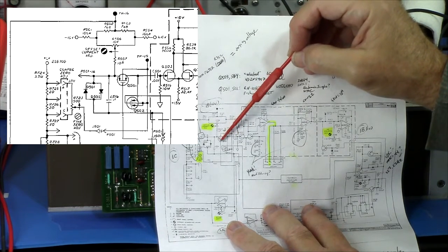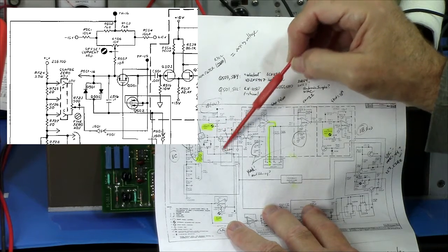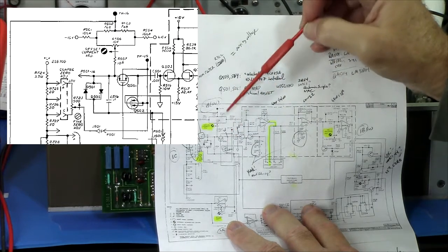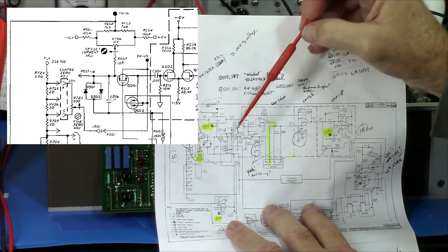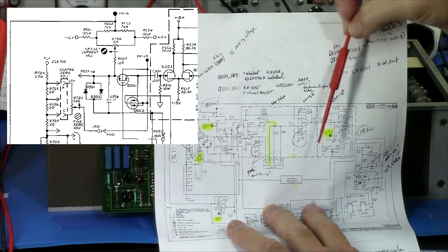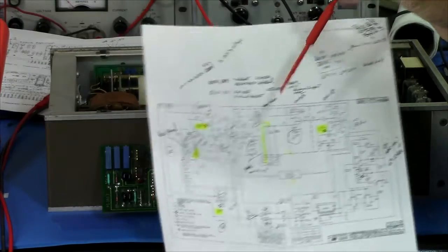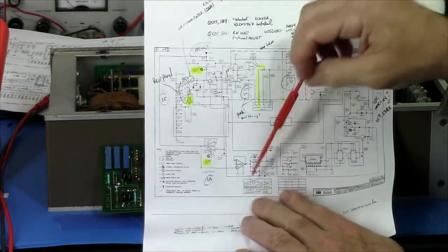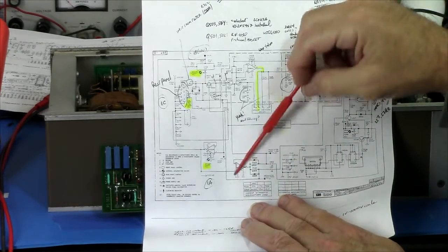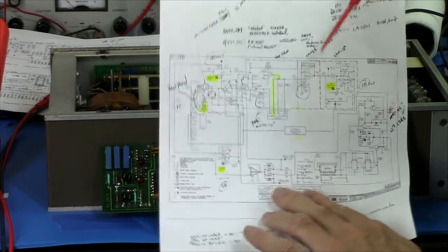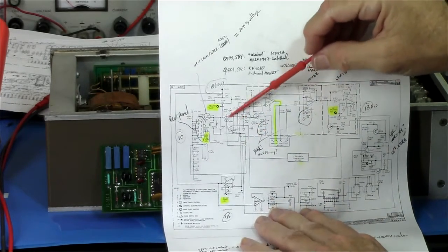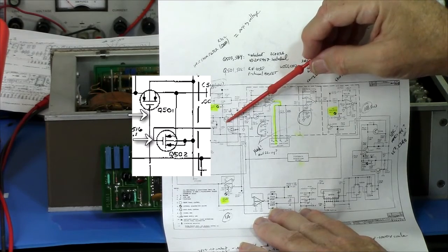So that says it almost has to be coming through one or both of these transistors. How can that happen? Well, I have a thought. They're switched. There's circuitry over here to switch them at a 227 hertz rate. And so there's a switching voltage that gets put on the gate.